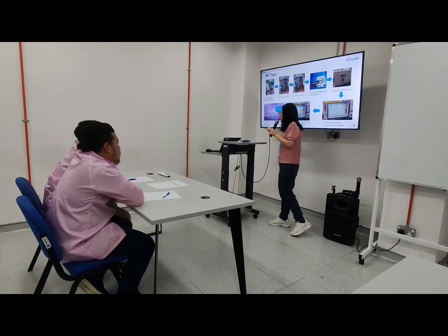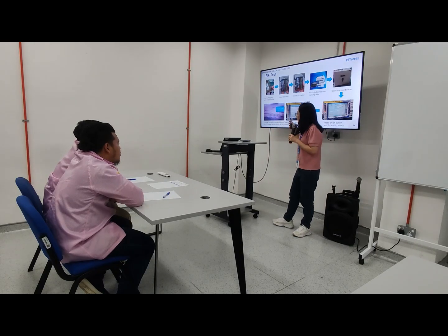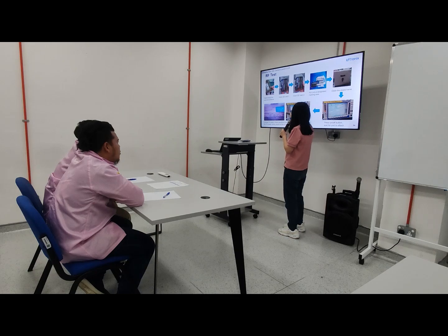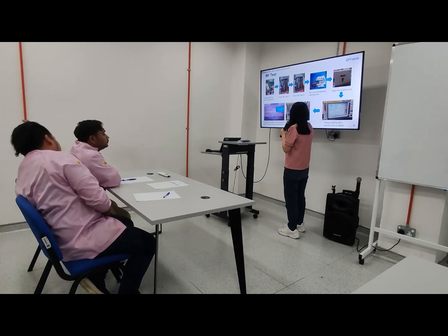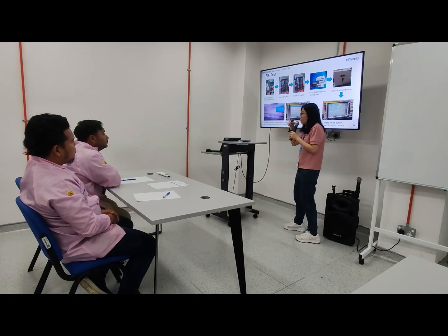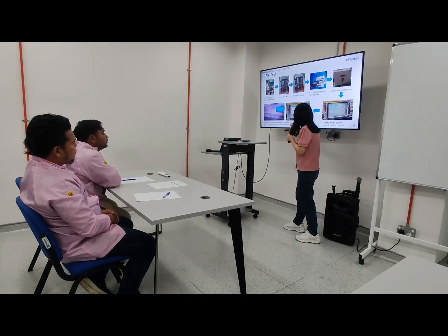First we will do the TX measure. Actually there are just two tests, TX and RX. So first we will do TX, and then we will check the waveform. The waveform must be like this, with no sudden peak. It must be almost the same level. No sudden peak. Even no abnormal peak, and then we check the power value. This one.